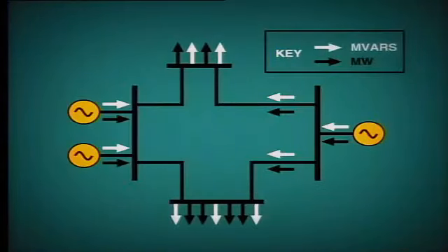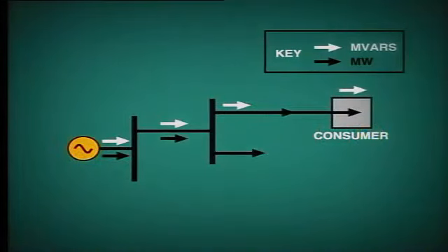So on our power system, we have a demand not only for active power, that is megawatts, but also for reactive power, or megavars, and both of these power components must be supplied by the generators. Fortunately, the provision of megavars does not require any increase in energy input to the turbines. The fact is, reactive power does not absorb any energy at all. The reactive power actually oscillates twice per cycle between the magnetic field of the generators and that of the consumer's equipment. The average power consumed is 0.